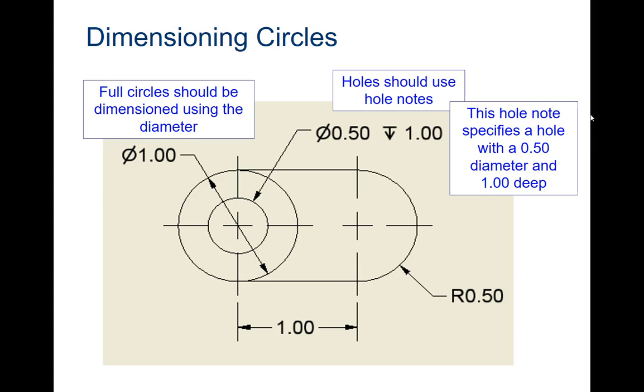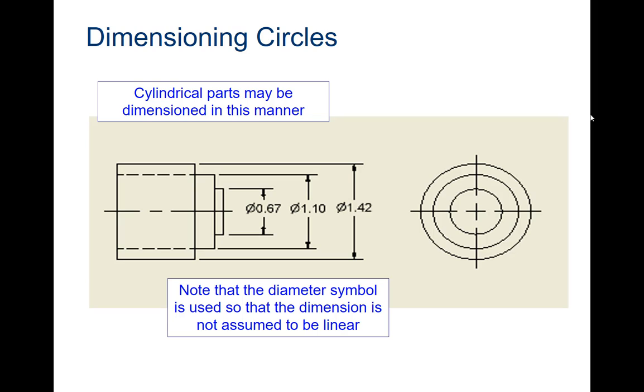Another way to do circles, if you've got a lot of them in like concentric circles, is to turn them sideways and do a dimension such as this. You could do leader lines out telling us the dimension of each one of these circles. That would be fine. But if I look at this one, I could do the dimension of each one of these circles, and then I could do along the top a width, and that would be all the dimensioning that I would need, because I would know how big each one is around and how deep each one is. I could also, if I had this drawing, just draw this shape right here, put in a center mark, and revolve it to make it very, very simple.